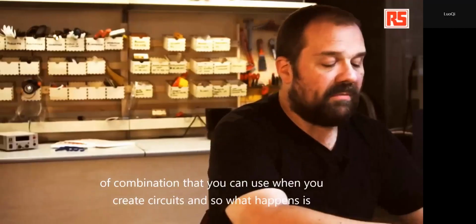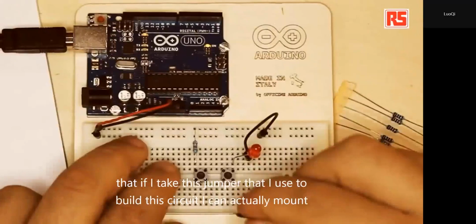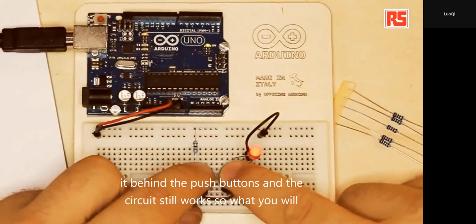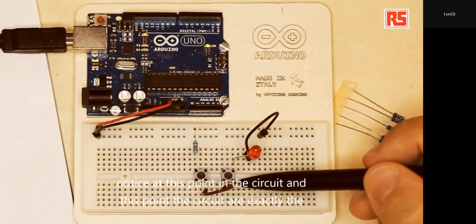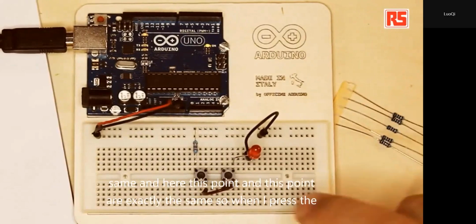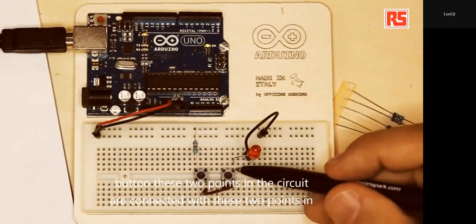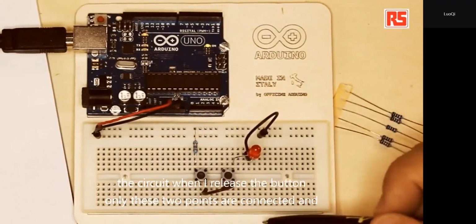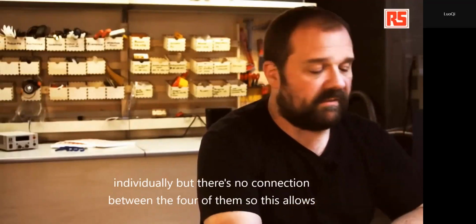And so what happens is that if I take this jumper that I used to build this circuit, I can actually mount it behind the push buttons, and the circuit still works. So what you will notice is that this point in the circuit and this point in the circuit are exactly the same. And here, this point and this point are exactly the same. So when I press the button, these 2 points in the circuit are connected with these 2 points in the circuit. When I release the button, only these 2 points are connected and these 2 points are connected individually, but there's no connection between the 4 of them.